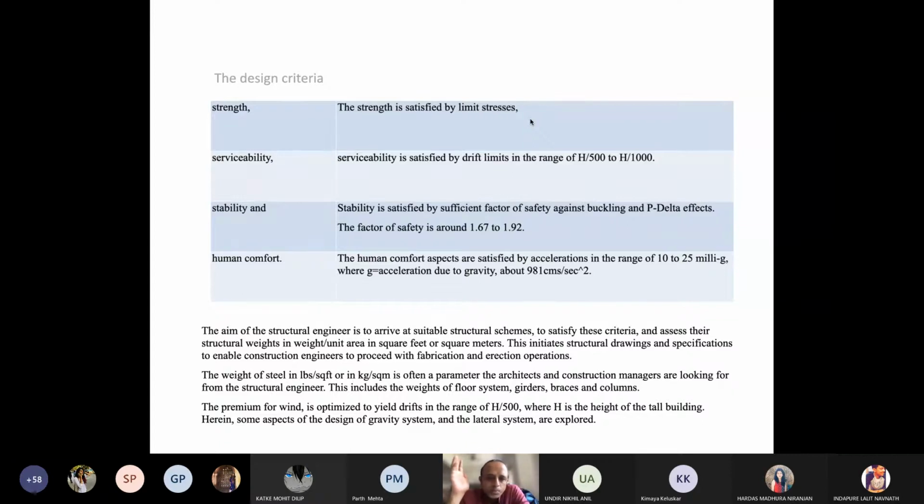You can understand the problem, because normally the lift shaft tolerance levels are a maximum of 25 or 30 millimeters. Over here, these are skyscrapers, which sway themselves, not just from construction fault, but sway to the tune of 200 millimeters. But that is the kind of tolerance, the kind of design that you have to work with.